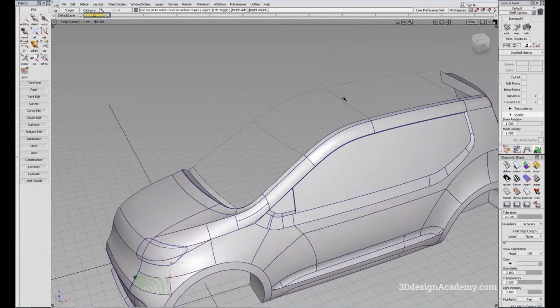Now, this is a little bit more advanced selection, but in Alias, you can set certain objects and curves as template and model. So let's say I want to make these two template. What template does is that it still displays the model, but it disables you from being able to actually select it. Now, this is actually quite useful if you have several models and you have a lot of detail.